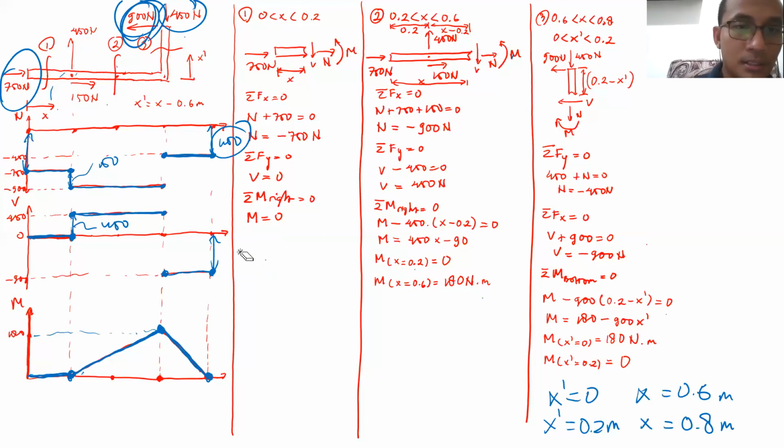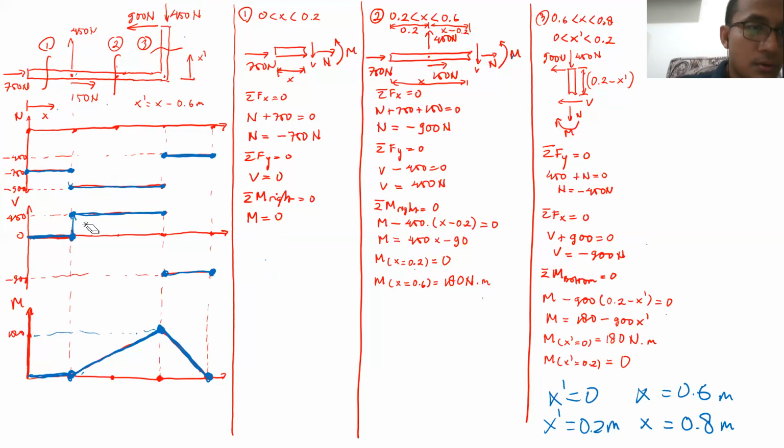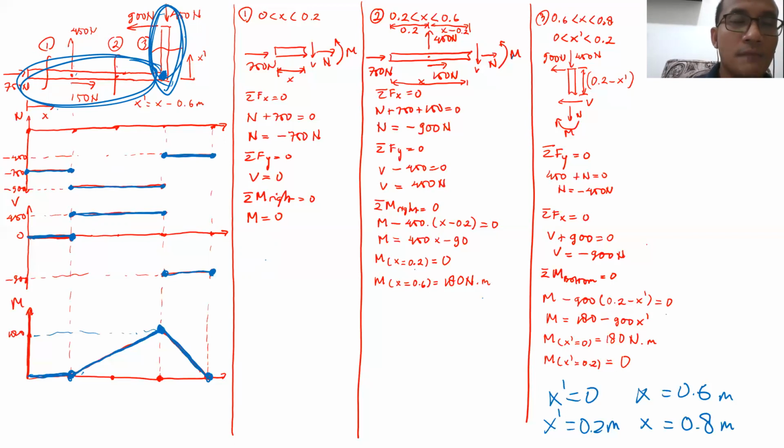But remember, when you think about it, don't apply that logic for this particular intersection, because there the normal force of the horizontal section will become shear force in the vertical section, and on the other hand, the shear force on the horizontal section will be the normal force on the vertical section.